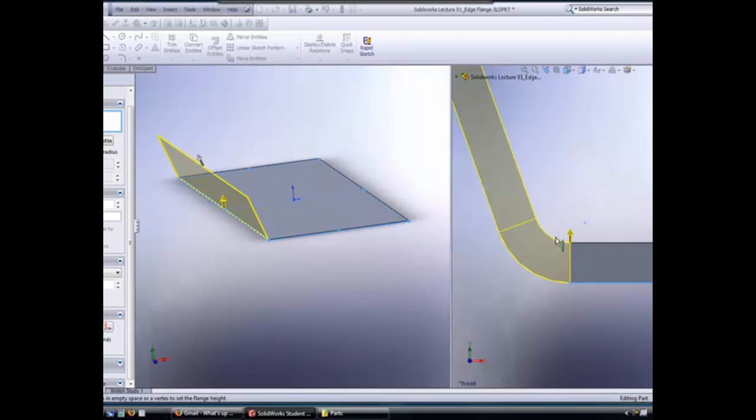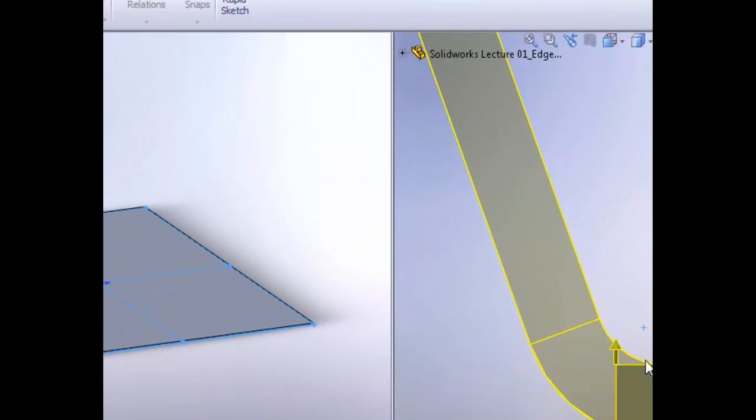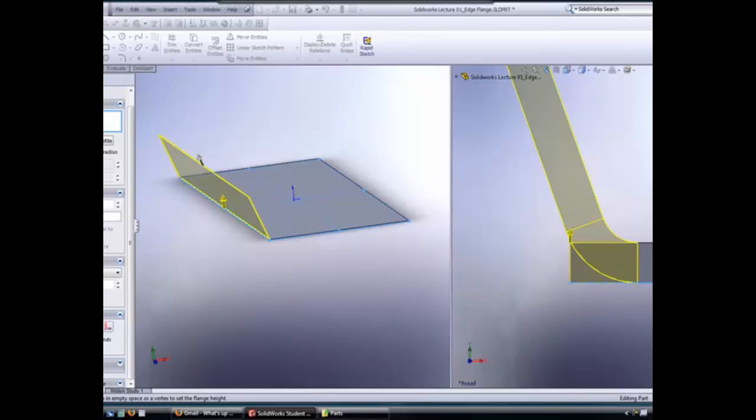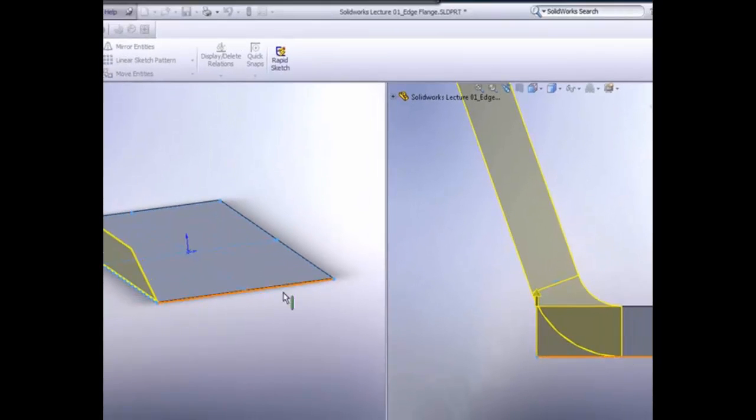So this is actually not what we want, first of all, because it's adding material to get that bend. If we have it bend on the outside, it's also adding a little bit of material, right? Because the bend itself requires the interior edge to be on the outside of this flange. So we're going to have it bend completely on the inside. That way we're never exceeding this 6-inch dimension that we assigned for this base material.